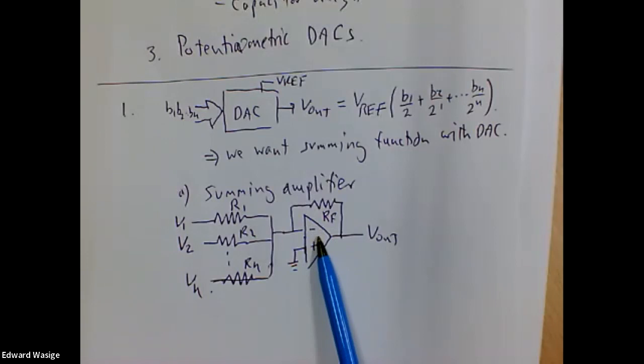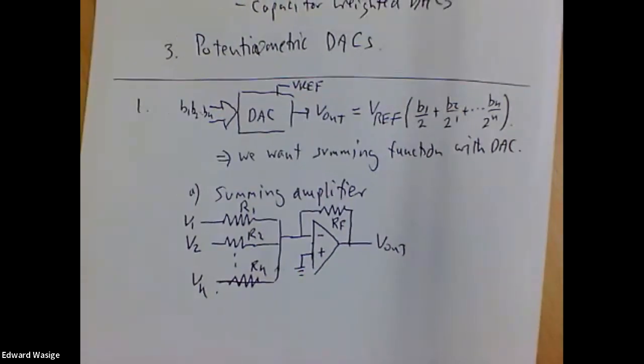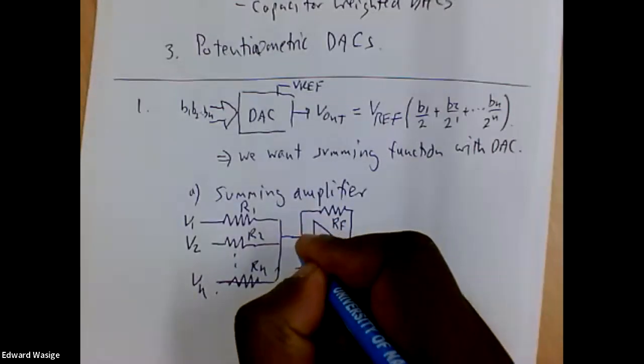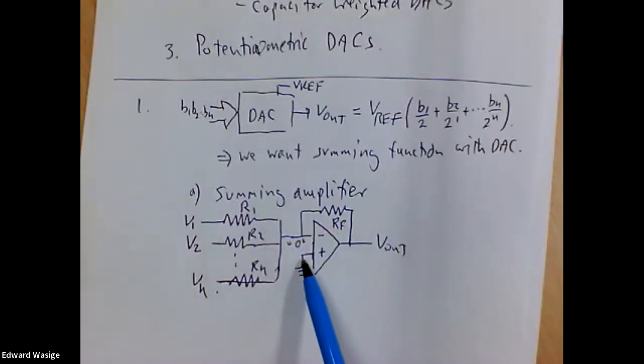So we know what's inside the op-amp. We spent almost 2 weeks or 2.5 weeks discussing the circuitry of the op-amp. If we connect it in this configuration, because this is a high gain unit, the potential difference between the two is close to 0. So the potential at this point is almost identical. It's almost ground, and we call this point a virtual ground.